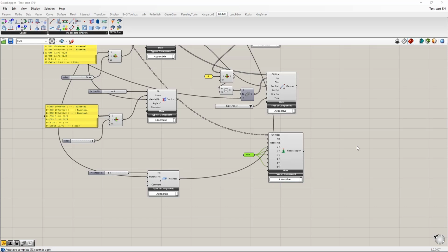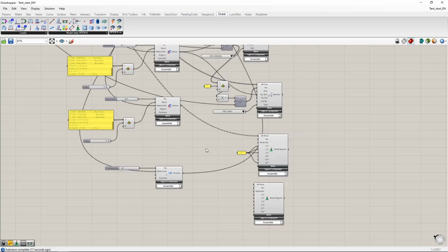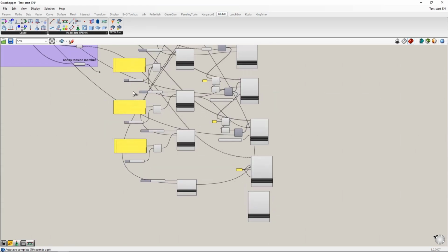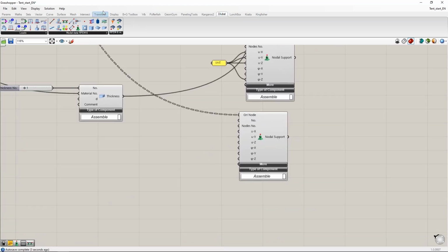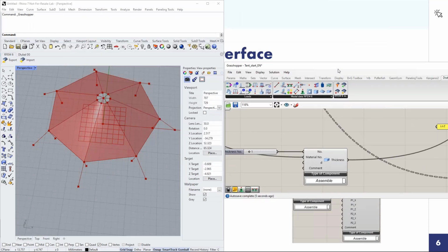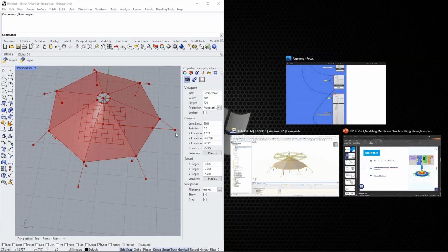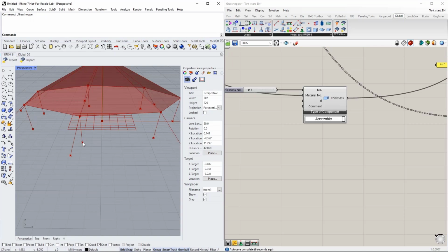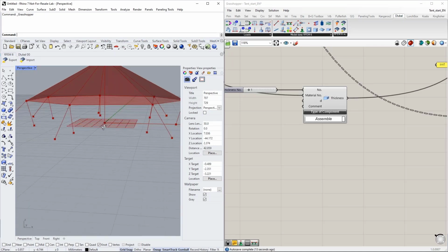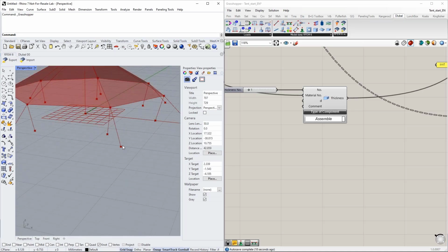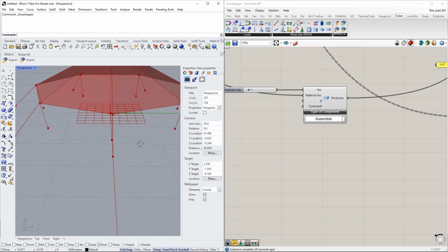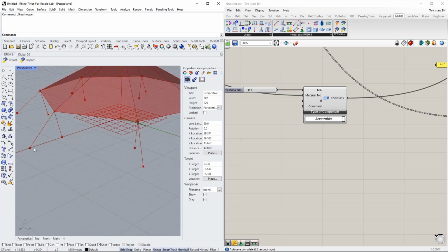And then I have one more set of nodal supports, and here I want to show a different option. My nodes are those nodes. And maybe to show it quickly here in Rhino. So the first set of nodes were for the column basis, for the bottom part of my columns. And now I define also supports for my tension members, which are these inclined members here.